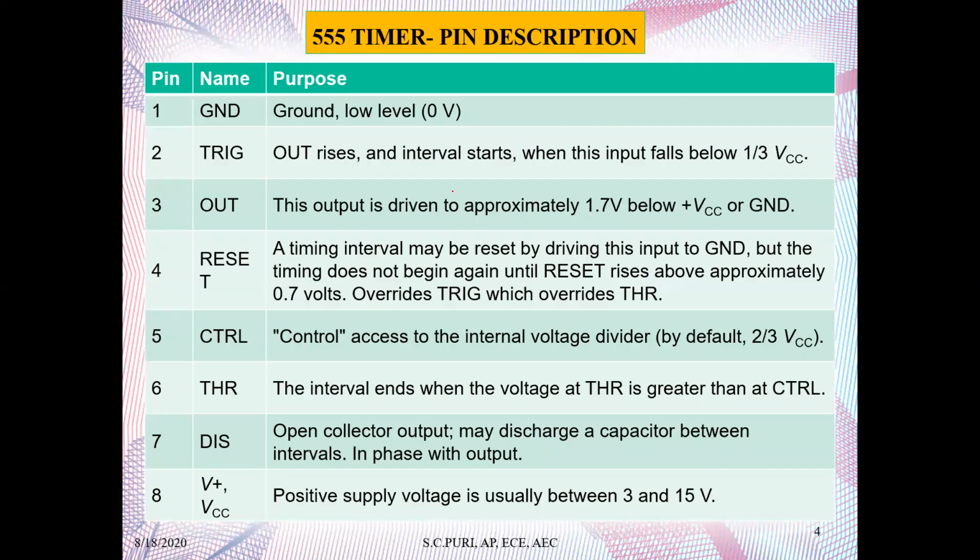Now, as I told you, this is the pin description. The ground pin is there. We talked about the trigger pin, the output pin, reset, control voltage, threshold, discharge, and finally the supply voltage. And these are the specifications.